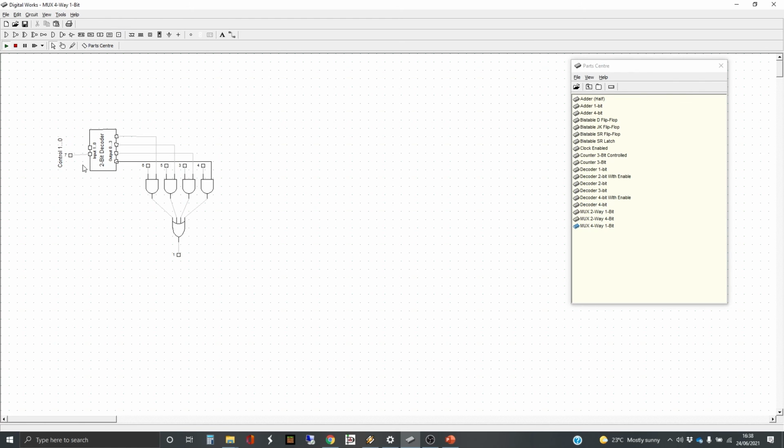Let's, for the sake of making this slightly easier, just get rid of both of those tags, and then we'll need to put two tags in. The reason why I'm deleting them is because I don't know if there's any way of disconnecting the tags from the pins in the template editor. If there is, I don't know how. So this is the way that I know how to do it.